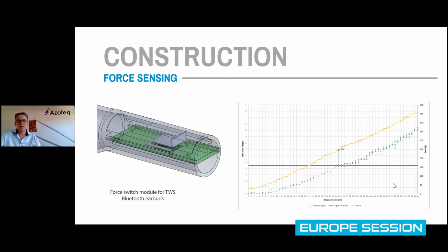If you have a controlled environment, if you know what the environment is like, then capacitive sensing is a very elegant technique, and it has a lot of advantages. But when the environment is uncontrolled, like this true wireless, maybe you are in a hot bus and you step out into the cold street, or it's raining, or it's snow, or it's gloves. You don't know. There's too many unknown factors. Then inductive sensing makes a lot of sense, over and above the advantages that it brings in terms of reliability. Yeah, I got it. Thank you very much, John.